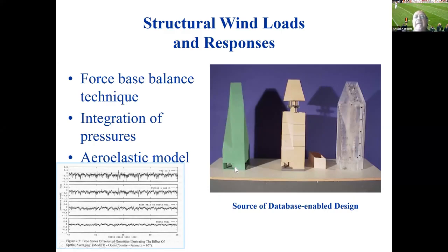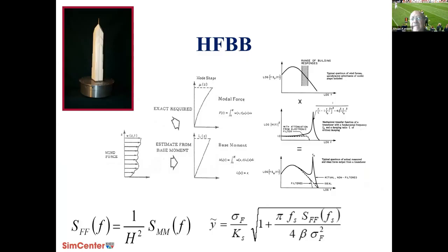So what it does is that the integrated effect of all the loads is monitored by that balance. And it so happens, I won't go into the details of the study here, but this is the building model on that one. What happens is if you develop an equation for the modal force of a building, which is sort of given by this very simple expression, and if you develop base bending moment caused by some arbitrary wind loads, they both happen to be only scaled by a factor of height of the building. So what they started doing was to measure the base moment divided by H, you got the generalized loading in any direction in the first mode.